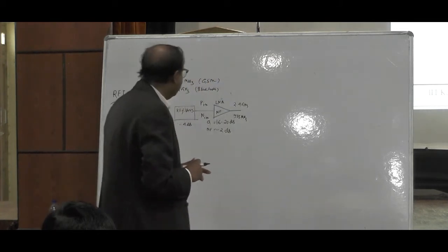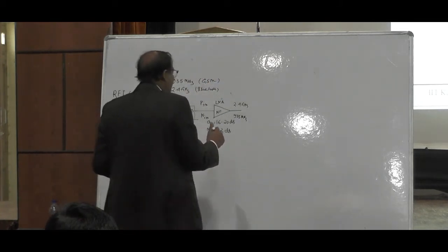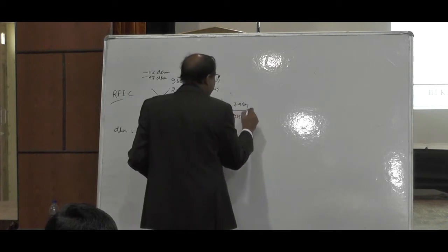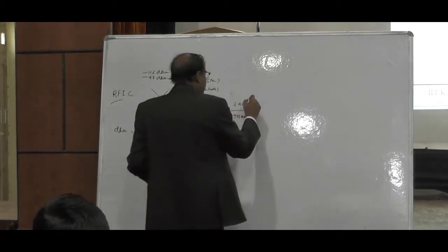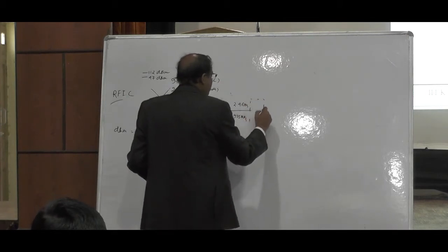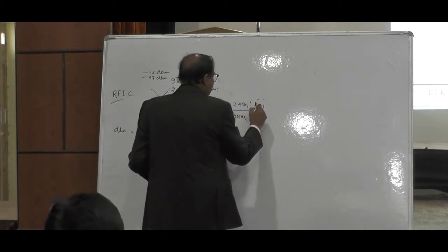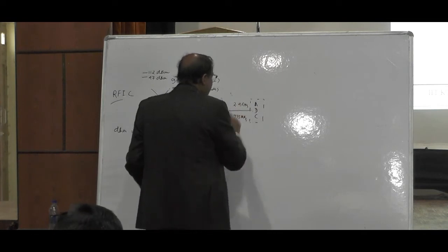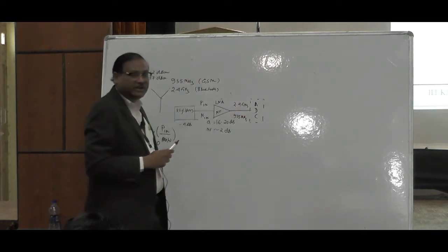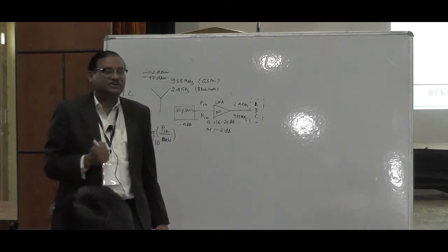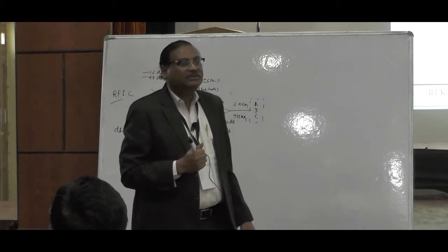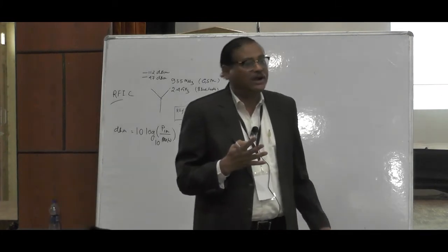Then you actually need an A to D converter of 2.4 gigahertz into 4.8 because of the Nyquist criteria. So imagine one A to D converter, the maximum frequency is 2.4. Straight away, if you want to convert to digital, then you need 5 gigahertz, or the data conversion rate will be so high.